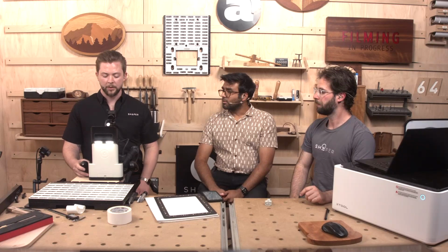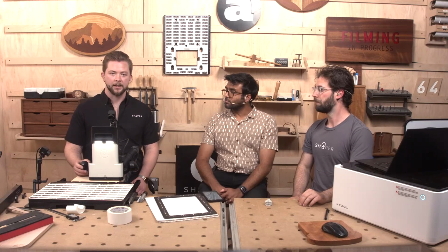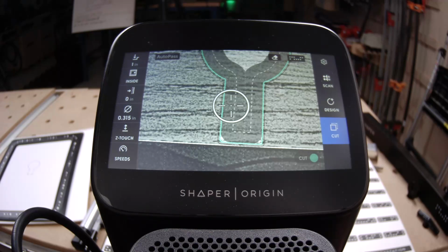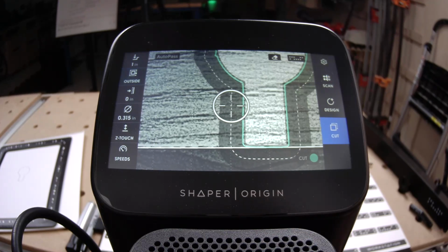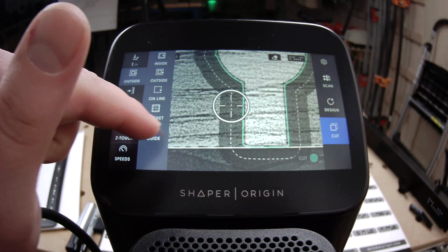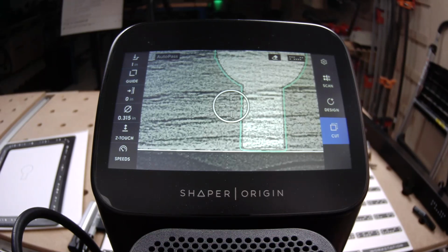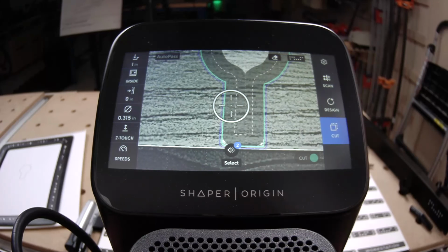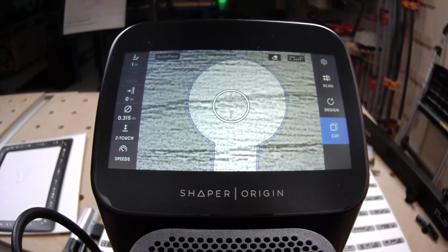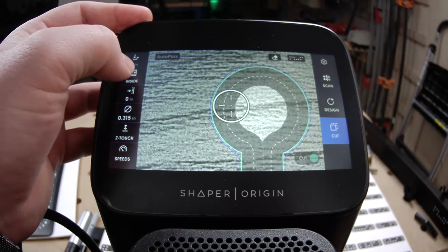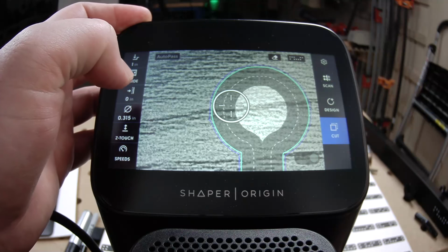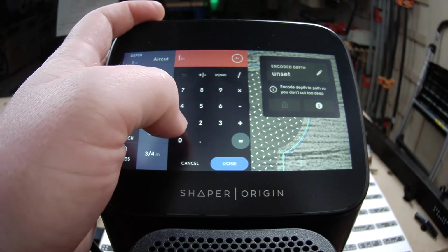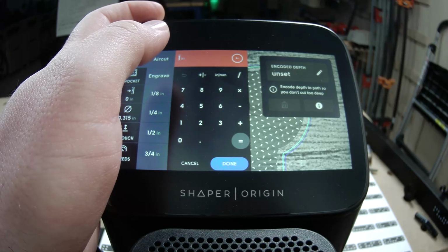Here's a little pro tip too. I am making sure that I select that inside line and turning it to an inside cut. Then I come over here to that outside line and just change it to a guide. Beautiful. Just to get rid of it. Yep. Or to make it not cuttable. I actually want to pocket this first. Okay. And this is going 21 millimeters deep eventually. I know that because someone put a nice note on the back of it. Wonderful.